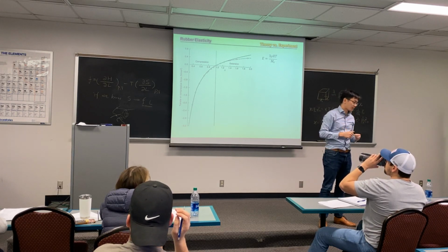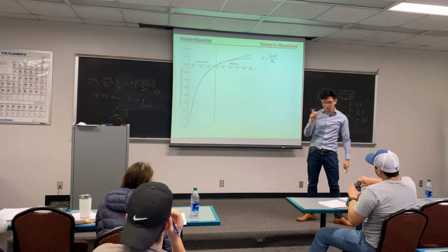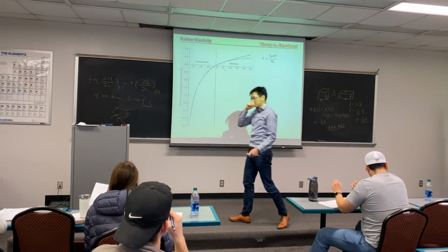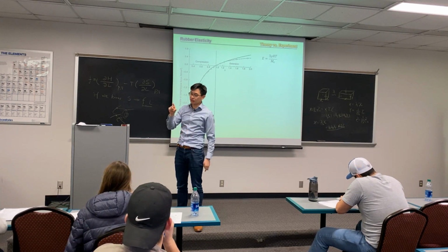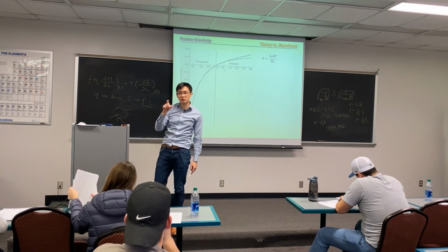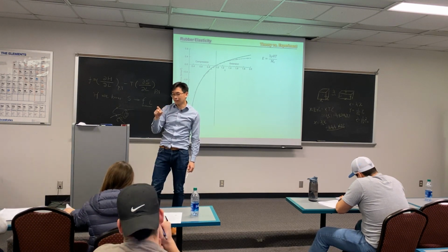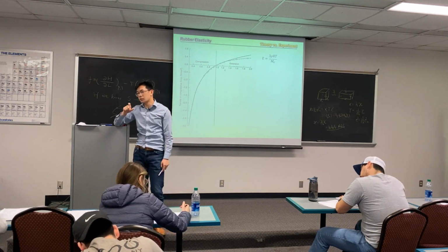Now you throw in the sulfur, you vulcanize them, you cross-link them. So a polymer chain typically has many cross-link points along it. It's segregated into individual polymer strands between the cross-link points. And for a lot of rubbers measured, if you check the literature, those are typically a few K.